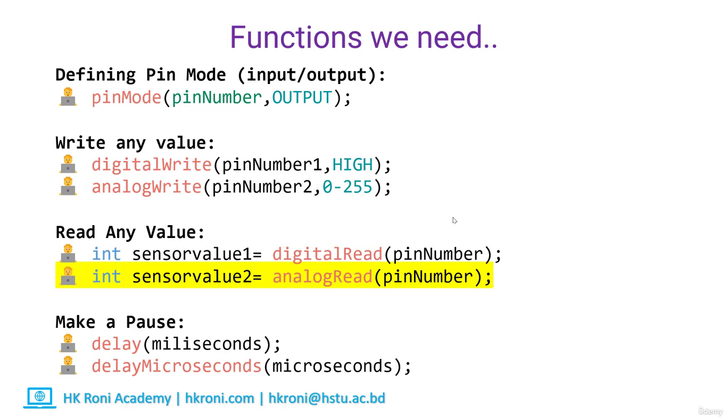Before going into the program, let me introduce the function called analogRead. So analogRead is basically used for reading analog values from analog sensors or analog inputs like a potentiometer. For the syntax, we need to write analogRead first, then in the bracket we need to give the pin number, that is A0 to A5, any of the pins that we will use for analog reading for Arduino Uno. For other boards, it could be different pins also. You can also store the value that you have read from the sensor into a variable. That variable data type could be integer, float, or any other format.